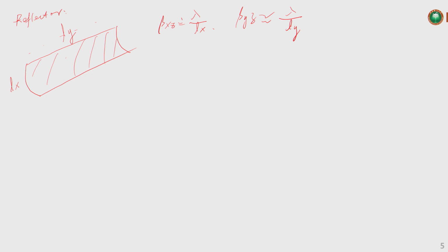So this is a rough expression, not the actual or exact values. When we want to calculate the exact value, theta x equals kx times lambda over Lx, and kx is a constant related to the stiffness of the taper.